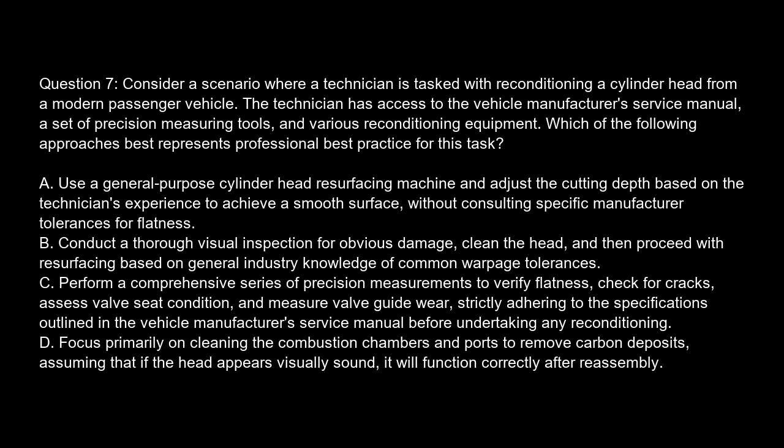Option A. Use a general-purpose cylinder head resurfacing machine and adjust the cutting depth based on the technician's experience to achieve a smooth surface without consulting specific manufacturer tolerances for flatness. Option B. Conduct a thorough visual inspection for obvious damage, clean the head, and then proceed with resurfacing based on general industry knowledge of common warpage tolerances.